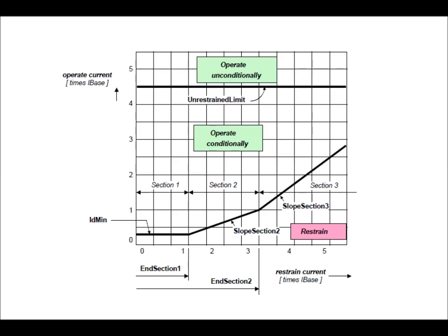But here the bias current is the percentage of the maximum of the full load current in the HV side. In RET670 and RET650, the bias current is the same, that is, it shows the maximum value of the HV side current. If red, yellow, blue phase currents are respectively 85, 90 and 88 ampere, then it will take the bias current as 90 ampere. That is, 90 ampere is the maximum of the HV red, yellow, blue phase currents. This is the characteristic of the RET670.